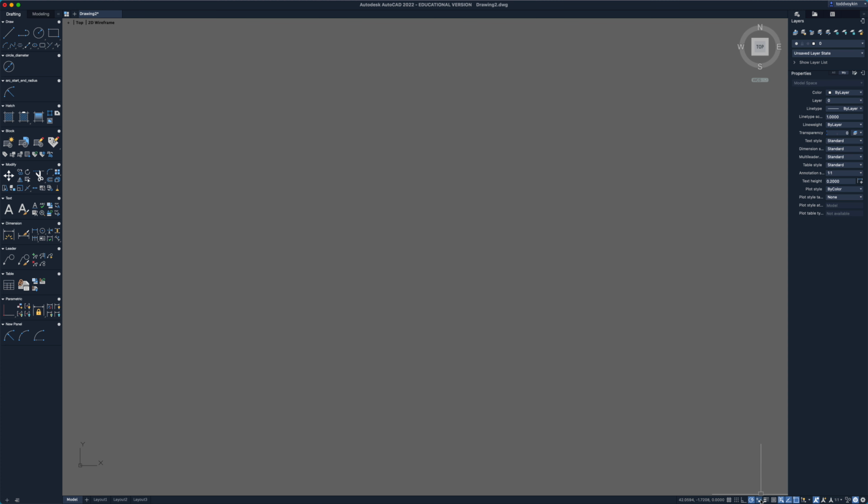Okay, now beside that right here is the dynamic input. That is what allows me to go into the middle of the screen and type a command, and it brings up this window giving me other information. And if I was to turn that off, I'm going to come up here and start typing, and it just doesn't work the same way, and it's very frustrating. So again, sometimes students will go down below and accidentally turn that off, and they're wondering why they can't access any of their shortcut commands anymore. And just be aware that you can just come down here and turn this on by clicking on it and ensuring that it is blue.